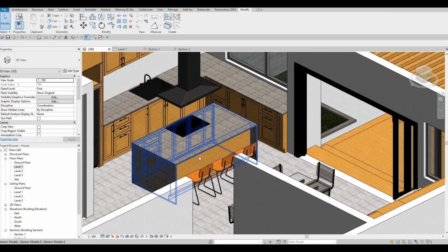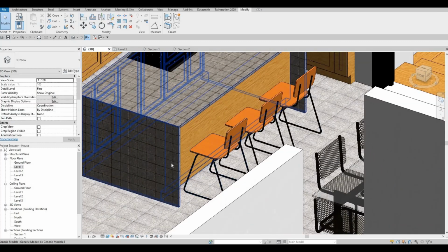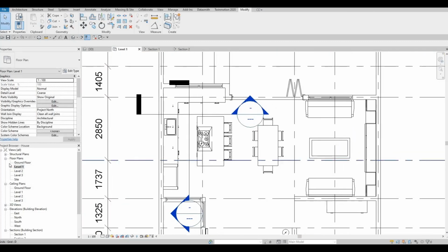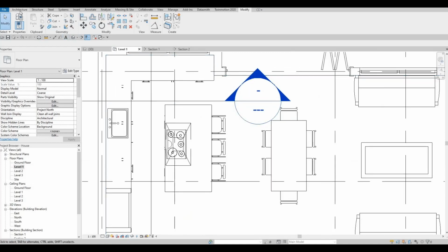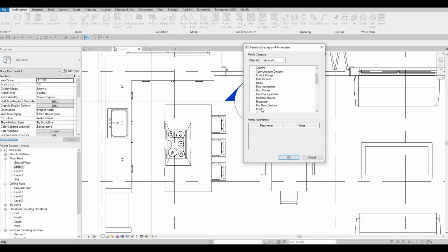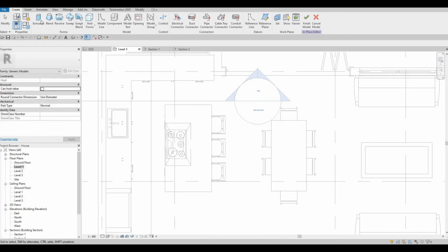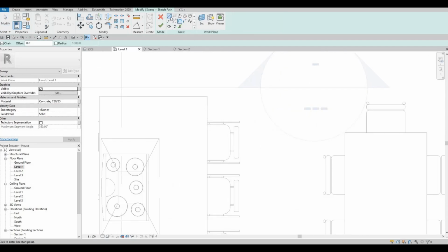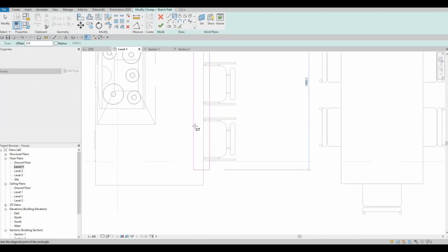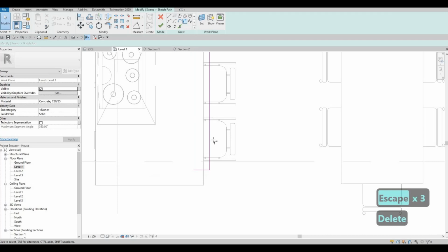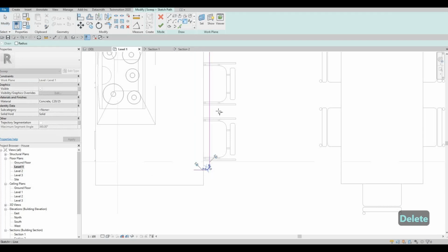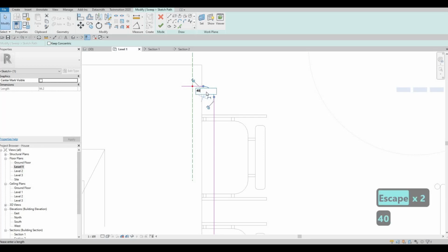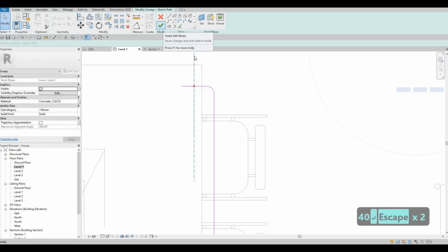And what I want to do next is to add maybe those knee rims here. So what I'm gonna do is go to level 1, and let's go model in place, generic model, and I'm gonna do a sweep, sketch path, and let's just maybe create this first, and then delete this, and then fillet arc here. So 40, and then here, make it 40 as well to be consistent. Click on finish.